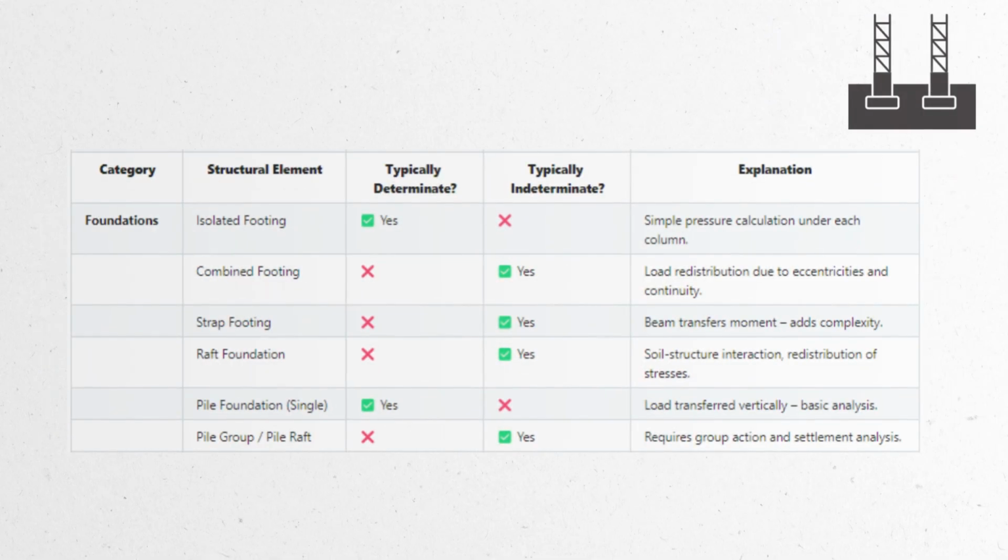Foundations. For foundations, determinacy depends on soil interaction and continuity. An isolated footing can behave close to determinate, but combined footings and raft foundations are highly indeterminate systems. This is because soil pressure is not uniform and settlement is not equal. So load redistribution occurs through the foundation system, which makes foundation design both structural and geotechnical.